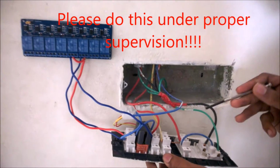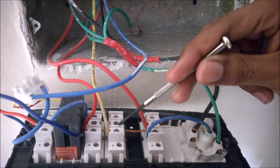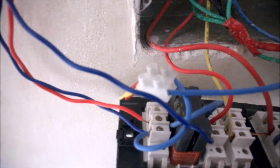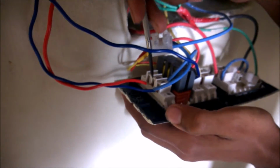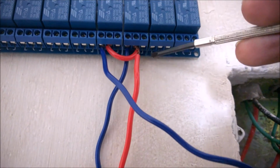Now, once you open your switchboard, you will see that there are two ports for each switch, and there is a single wire that is commonly connected for all switches. So what you do is take a wire and connect it to this common, and the other end of the wire you connect to the common of the relay module.